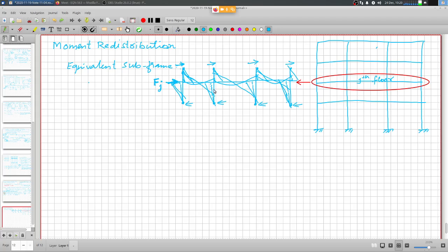Interior joint columns, because of the counterbalancing action of the beams framing into interior columns, the net effect on the columns would be very small. So the additional axial force on the column because of the flexural action from earthquake effects is going to be very small. So not much needs to be done for the axial capacity of the interior columns.